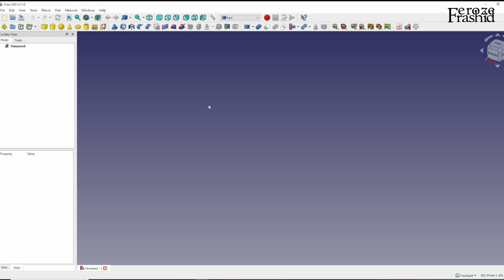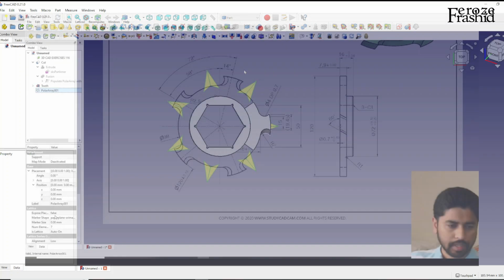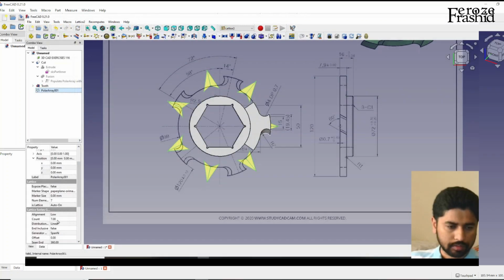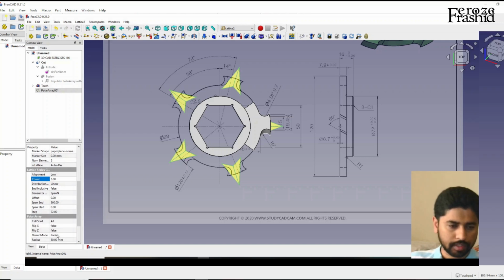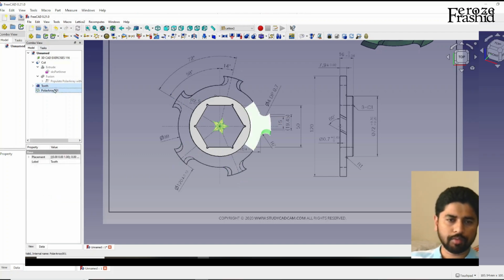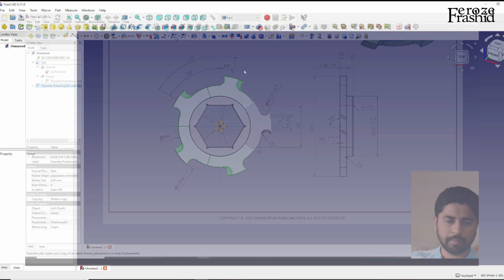So I'll talk about the basics of Lattice2 now. Lattice2 makes things easier by letting you only model part of the object and then replicate it several times. Like the most frequent Lattice2 example is building a gear, where we build only half a tooth and then replicate it like 5, 10, 50 times to make it a gear.